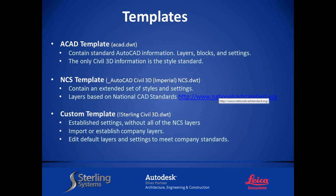Three templates are available to you. The first one is a CAD template, an AutoCAD template. The problem with this would be if you open up AutoCAD right out of the box and you started using the CAD template, there's no layers in there, so everything you draw would be on layer 0 and everything would be white. Same with the AutoCAD template. The only styles you have are standard, so everything you design or show is going to be white. This is not going to work for you.